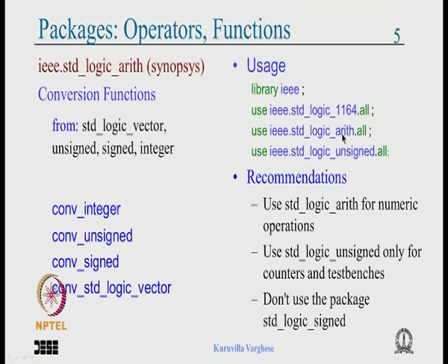You use basically arith for numeric operation, that is why it is put at the top of the unsigned. For counters and test bench you do not use this arith, you just use the unsigned, and do not use the package standard logic signed at all.